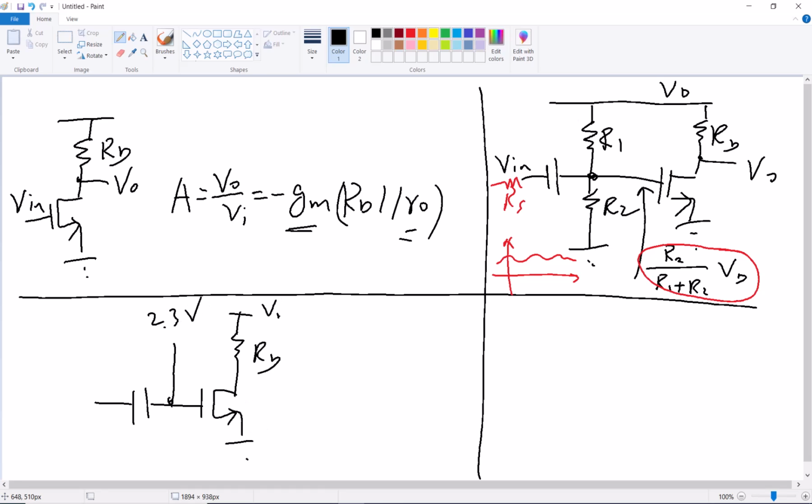And this is VDD, this is Vout, this is Vin. This is also okay, but then I need an extra pin. Later you will see the pin is going to occupy a large area in our design, because we need to have a large pad. So I don't want to waste the pin; I save the area for other purposes. Later you will see the layouts of the whole chip.